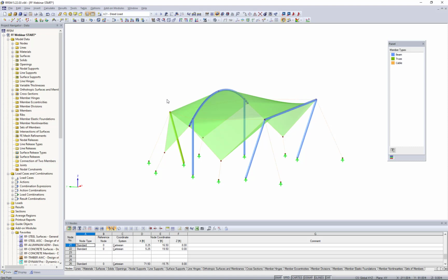This add-on module essentially allows us to define predefined properties such as these pre-stress forces, cable sags, and so on, and it will find the deformed mesh for us before we continue on with the static analysis. A simple way to explain this is the cable elements are completely straight. Form finding will allow us to define a cable sag, for example. We run the form finding process, and then the program will come up with the catenary shape for us.